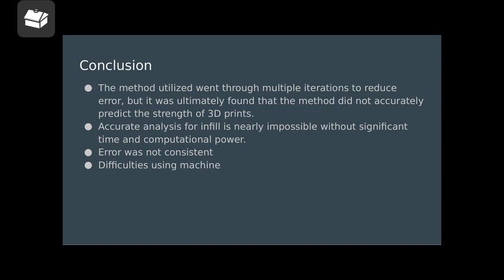Coming from this, accurate analysis for infill is nearly impossible without significant time and computational power. Throughout this experiment, we tried multiple times to get a better computational model to display infill, and we were unable to without significant time investment, as 3D prints have walls and an infill percentage, and this is extremely hard to model, especially when it comes to gyroid, which is a 3D shape that is somewhat helix-like. It's extremely difficult to model and to work with.